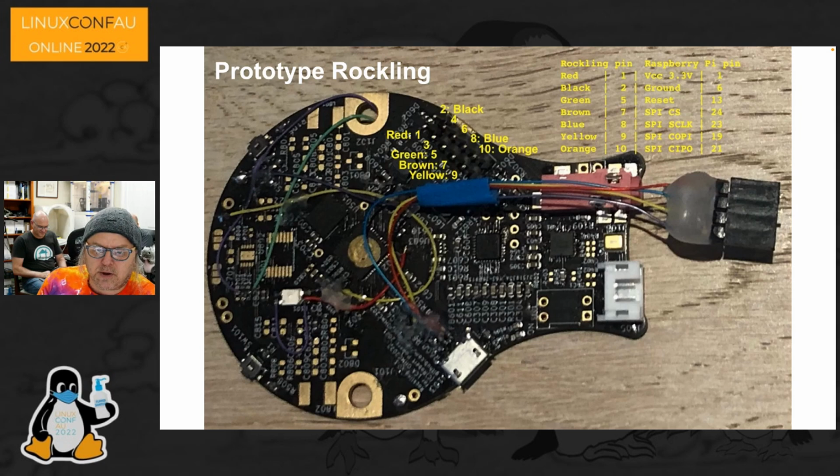That was encouraging. And then one of the key things we wanted to do was make it easier to flash and interact with the chip. So we put a header on the Rockling, which gives us both I2C and SPI. That would make it easy for us to reflash the bootloader, and also to interact with the device over a SAO from the swag badge.